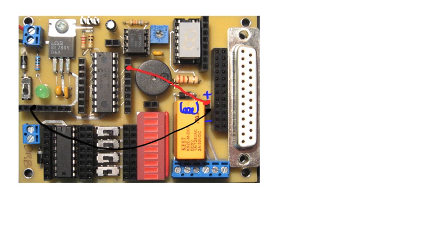This would work with some devices, but for this particular relay and coil and microcontroller, this cannot provide enough current to drive this coil, this relay. Remember that a microcontroller is limited in how much it can source and how much it can sink. And in this example, we have it connected up for sourcing. The microcontroller needs to provide the necessary voltage and current to turn on the device. With this particular relay, this particular microcontroller, not enough current will be provided to energize it. So we cannot use this technique with this setup in order to make this relay work.